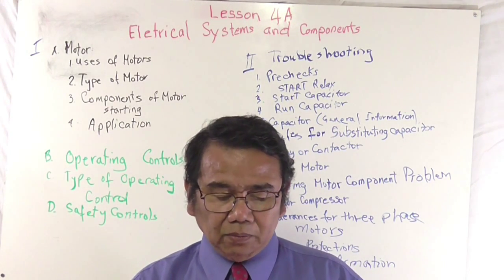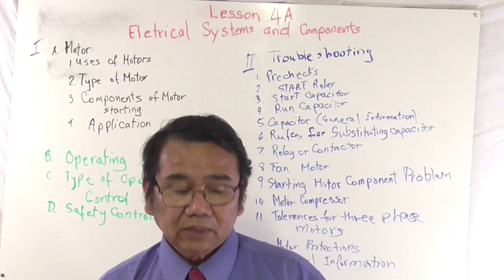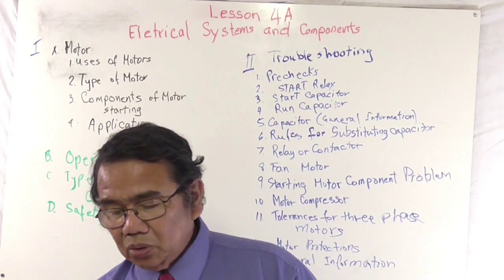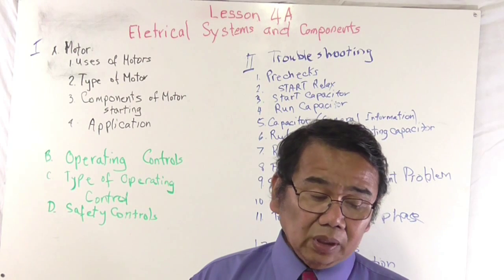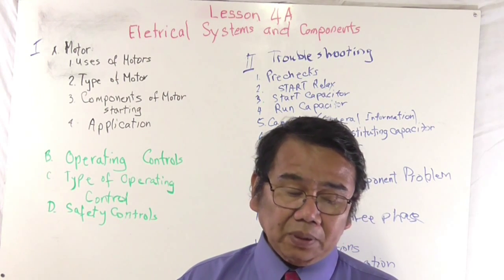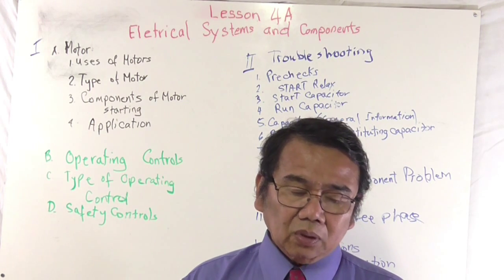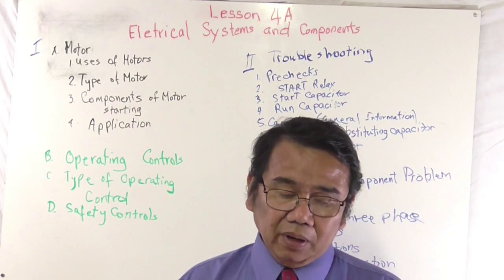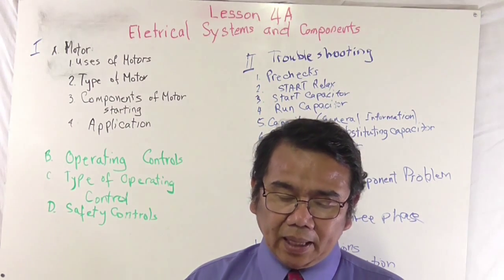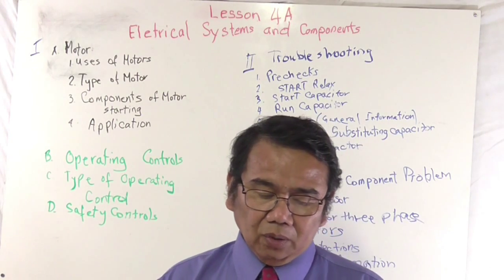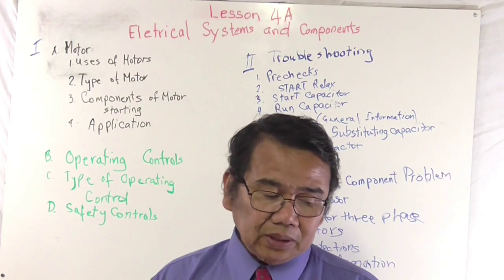And then the next problem will be incorrect voltage to the potential start relay coil. If the relay has been changed to one having a higher operating voltage or longer contact opening pickup time, the motor will run at too high a speed before the contacts open. Very noisy motor, wiping and breaking of compressor parts, rupture of the start capacitor.